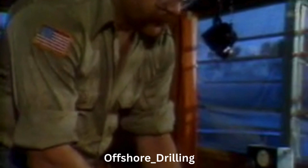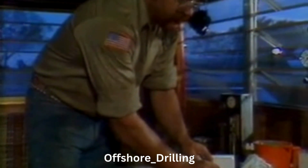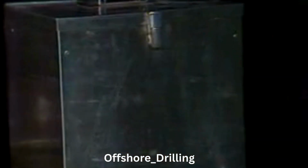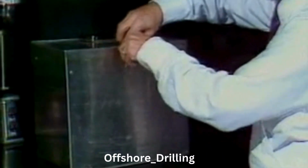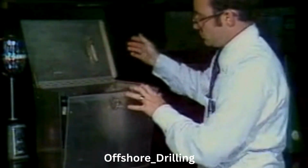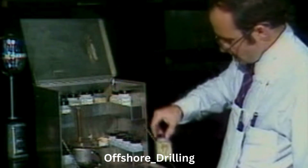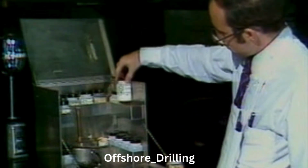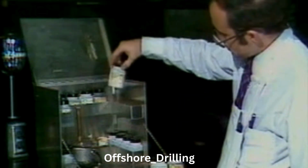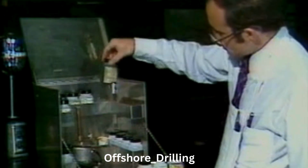Once the mud engineer has run all his tests, he'll have a pretty good idea as to what's going on with the mud downhole, and he'll be asking you to make adjustments in the mud from time to time. One final thing that is sort of a last resort, the mud engineer will probably have one of these kits. It's just a cabinet that contains samples of all the mud additives. If he runs into a problem that he can't figure out by using his tests, he'll start experimenting with a little of this and a lot of that until he finds a cure. So you might get into quite a few exotic additives from time to time.